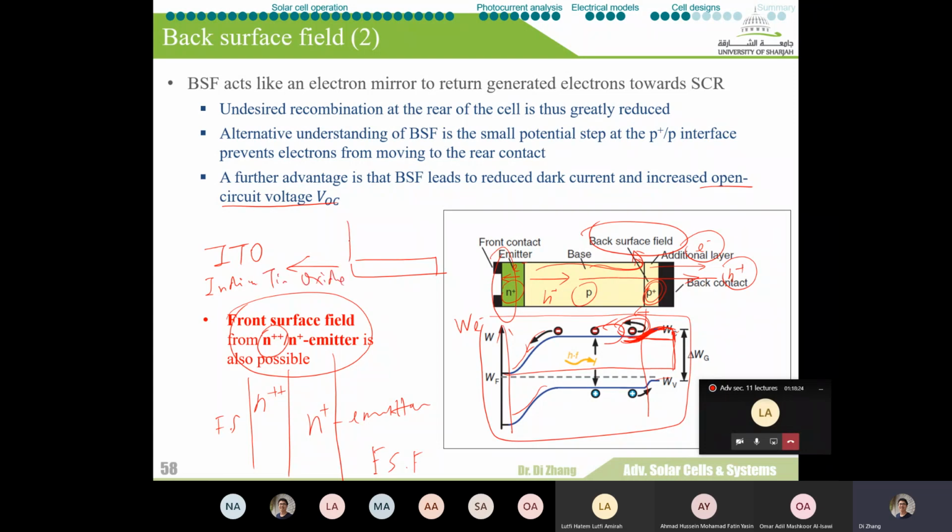You can search about it, but a very common concern for this ITO electrode is that the indium ions have the tendency to diffuse into the solar cell layer, and then it's going to cause some unwanted phenomena inside the solar cell layer. So these things can happen. Typically, if you worry about this phenomenon, you do have to come up with some methods to prevent them. So yes, it is a concern in solar cells. It's a very good observation. Okay, thank you, Doctor. No worries.